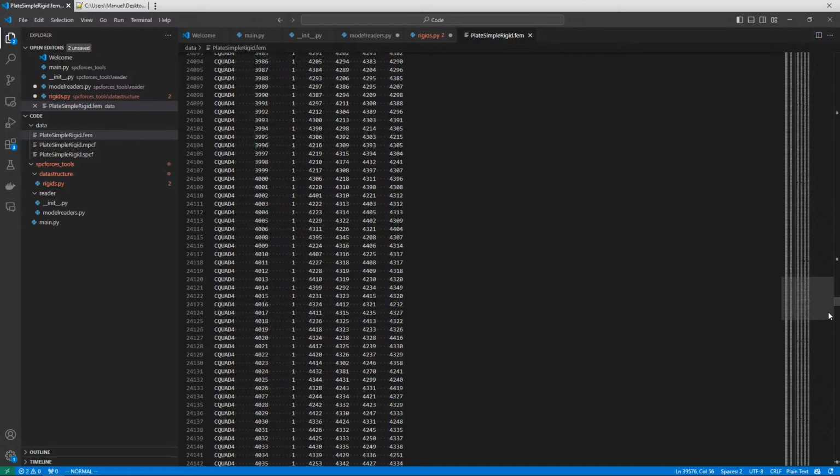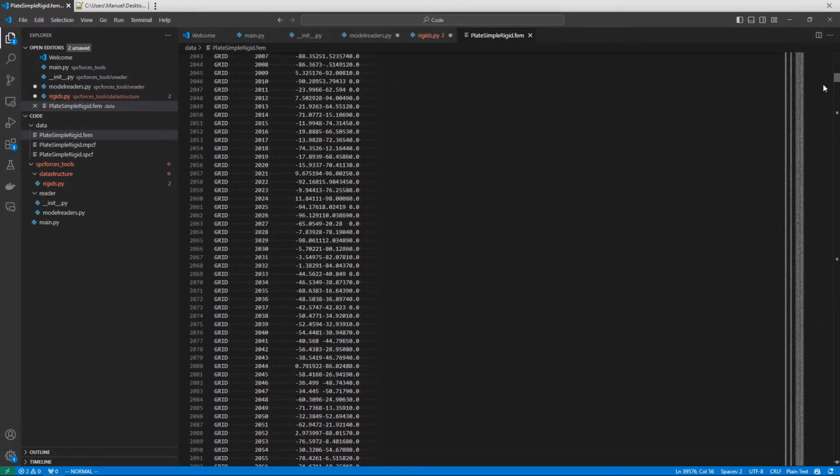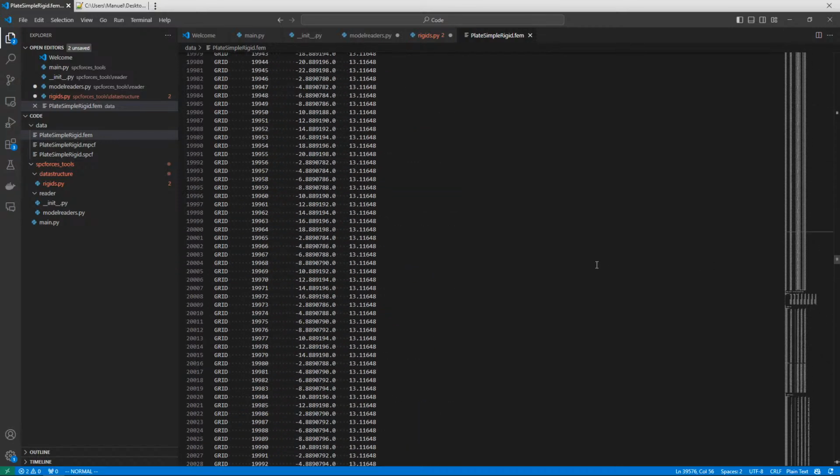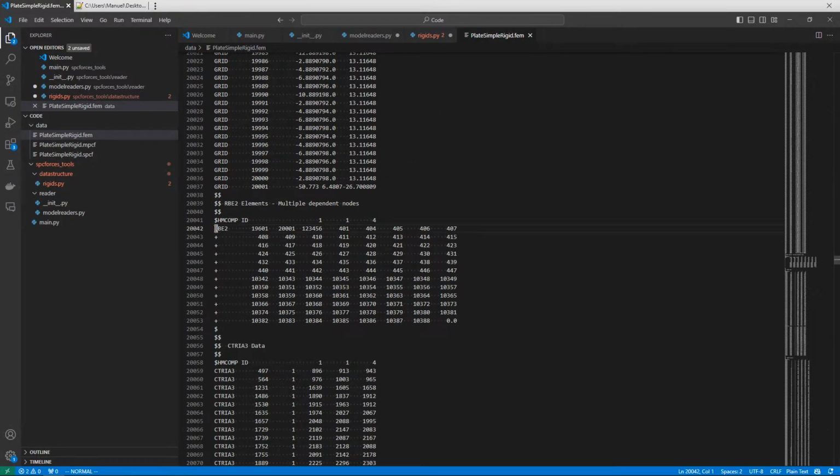So the FEM file, just think about this line here. Grids. Think about this file's lines. So we would like to have something, this is the ID of it, and then those are the nodes, and those are the coefficients, something like this. I don't know if there's something more to this, but we would have to look into the card information on the internet to get that, but pretty sure that those are the node IDs until here, and this is the element ID.